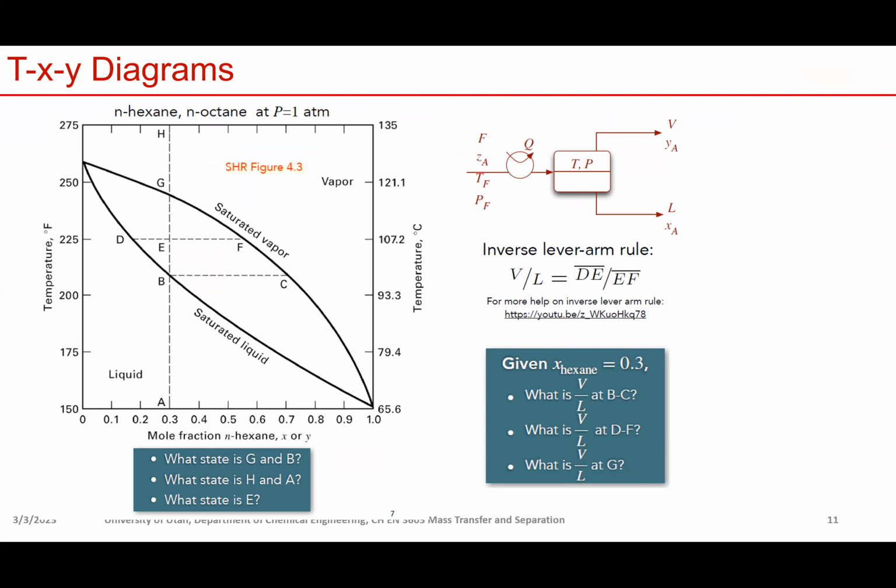First of all, on the XY diagram, any point on the equilibrium line gives us a composition. For a binary liquid-vapor phase system, every point on the XY diagram gives us the equilibrium composition of the liquid and vapor phase, and it also has the information of the temperature, right? Which is to say that if you draw a horizontal line here, you will get 2 points, and those 2 points will be plotted on the XY diagram, right?